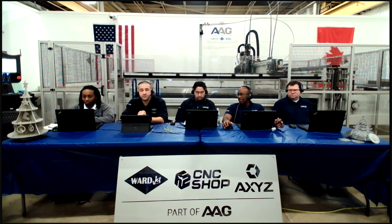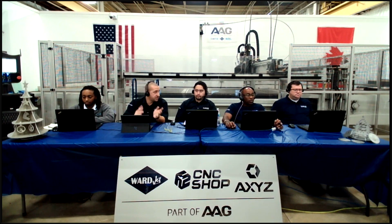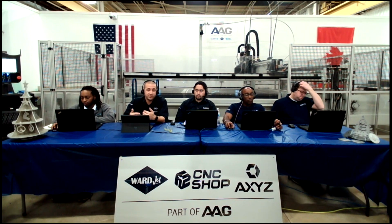Yes. So all of our X series platform, that's going to be kind of your standard footprint for water jetting. We've got that in a 5x5, 5x10, 6x12 and above. So to answer your question, a 10-inch piece absolutely would fit on an X series if you're doing 5-axis. We have standard Z travel of 12 inches on our machines. So with waterjet, really the only limitation to what you can cut is going to be what you can get under the head and how patient you are. So clearly we can fit that material under there.